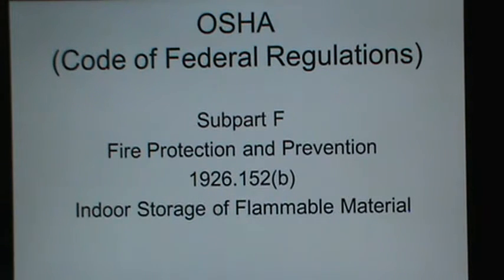The very next paragraph talks about indoor storage of flammable and combustible liquids. Not more than 25 gallons of flammable or combustible liquids shall be stored in a room outside of an approved storage cabinet. For storage of liquefied petroleum gas, you got to go to another section there.